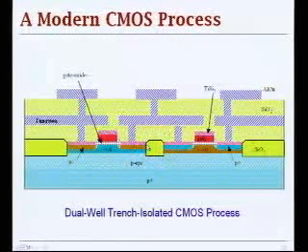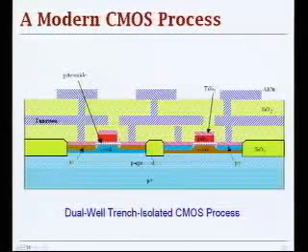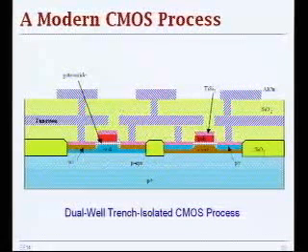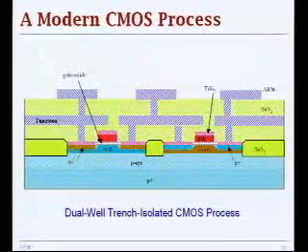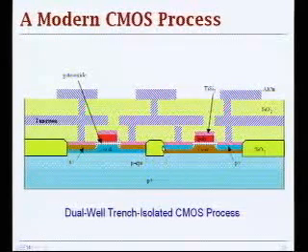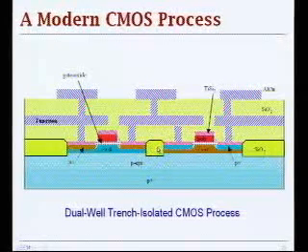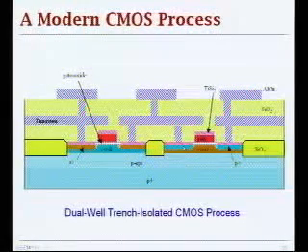Now manufacturing processes improved dramatically, so we can do dry etching, plasma etching. So you can drill through the material in a very precise way, and you can form these trenches that you later fill with silicon dioxide, and you can have much tighter spacing between the two transistors, which also increases your density.